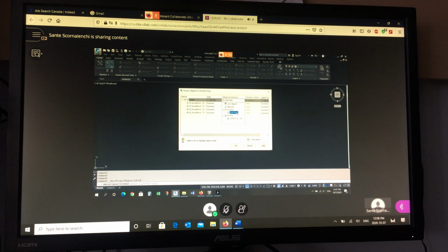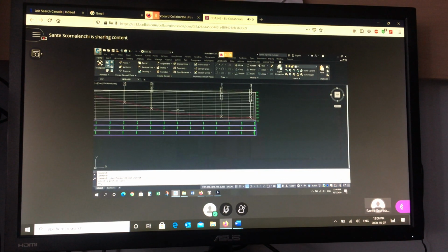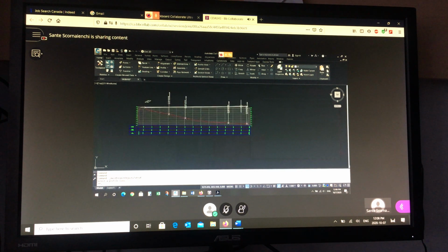They'll be close to my surface, right? Elevation from existing ground. And now it changes the elevation. So instead of 0, which is what's in the plan, it's going to get the station values from the alignment, but it's going to get the elevations from the existing ground. So watch what happens now. They're all in range, and they should all be kind of touching the existing ground. And then you don't get that huge grid that I just showed. Okay, so I'm going to delete this.